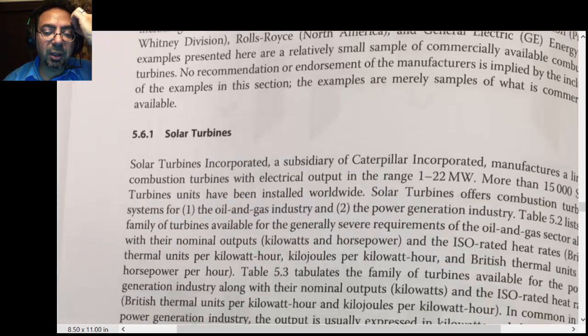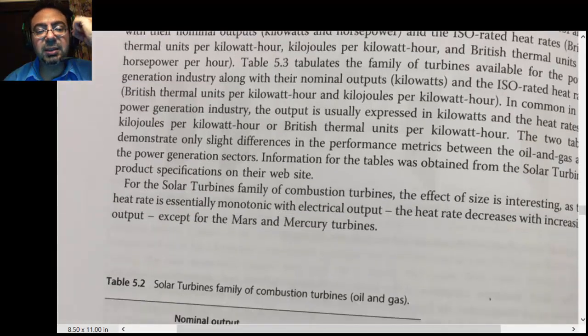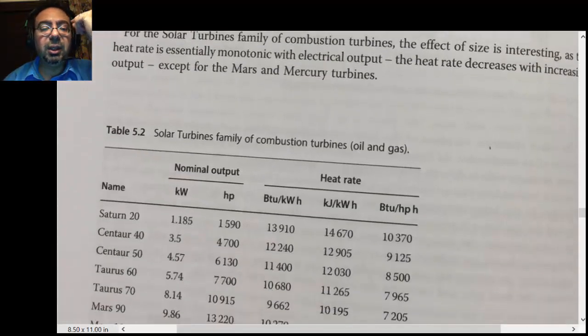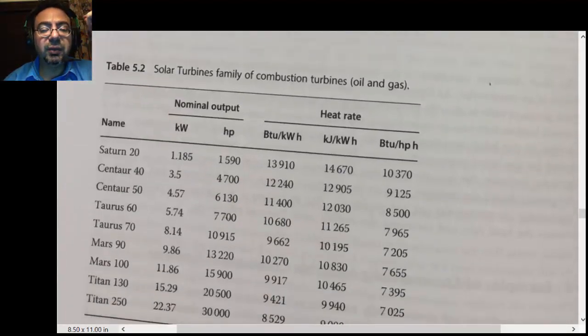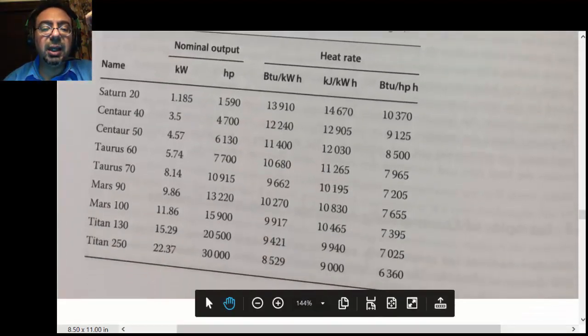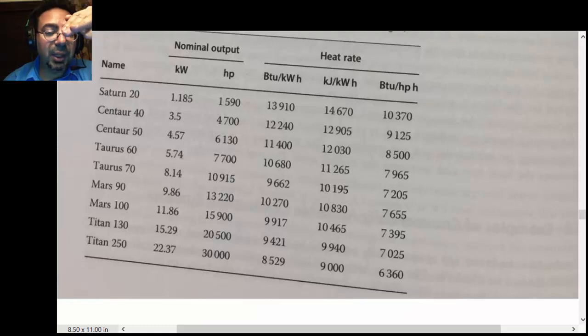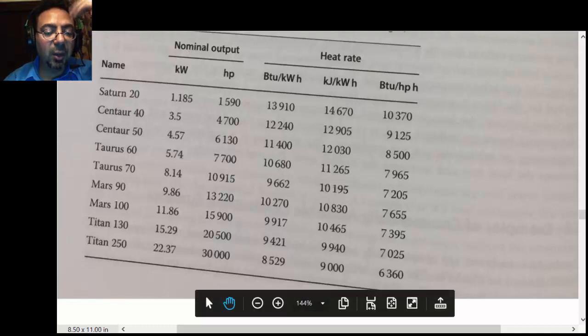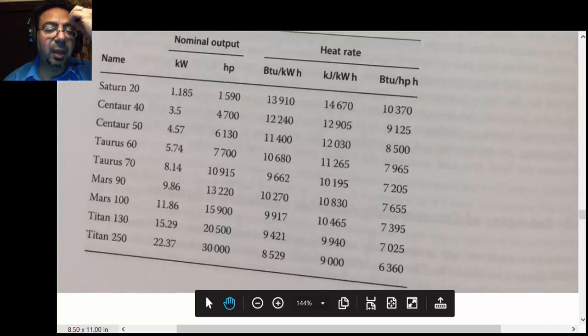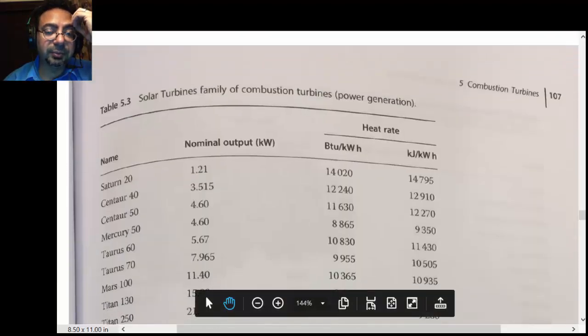So he finished by showing us an example of gas turbines already in service, and you can see the best of them can drop their heat rate to what, 8,000 to 9,000 BTU per kilowatt hour. So those are impressive, right? When the heat rate drops that low. When they are big, that's horrible, right? When they are getting really small, they become comparable to a steam power plant.